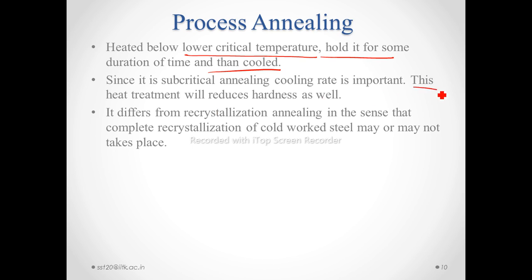This heat treatment reduces hardness, similar to recrystallization annealing. But there is no change in the microstructure because we are heating below the lower critical temperature. It is different from recrystallization annealing. Here there may or may not be a chance of getting new grains.